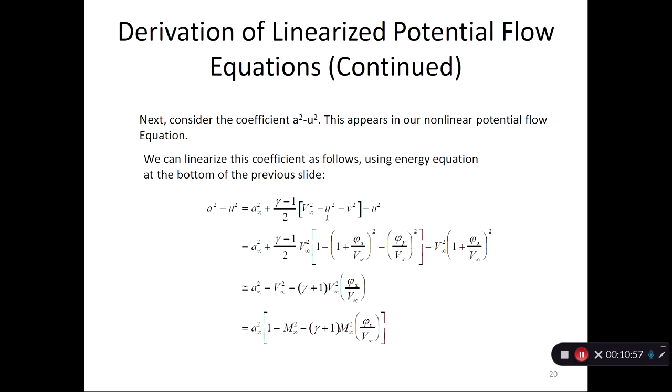Now u is free stream velocity plus disturbance velocity. Therefore u squared is that combination squared. So if you bring the free stream velocity squared outside, you'll get 1 plus disturbance velocity over V infinity, whole thing squared. Okay. So little u is V infinity plus Vx.